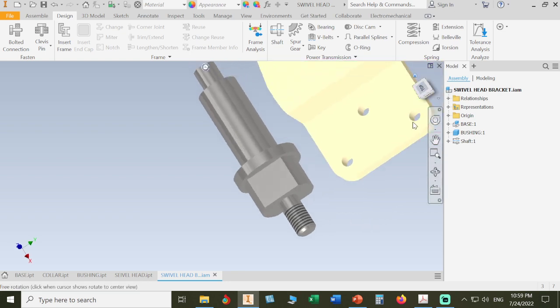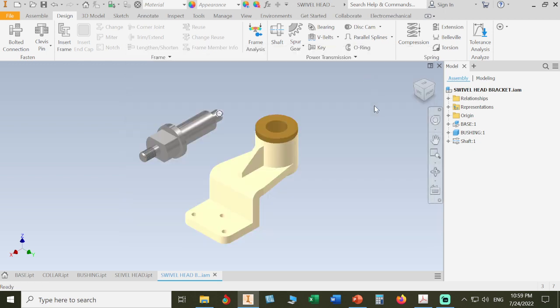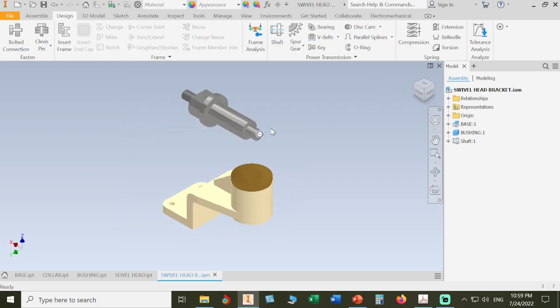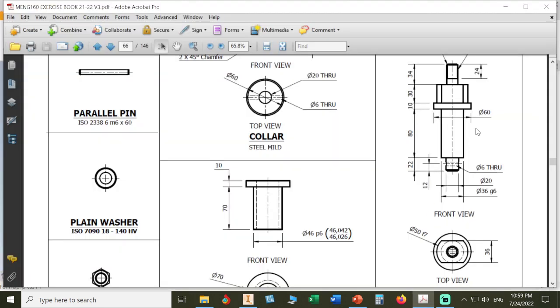Next. Save. Okay. What else can we do with our shaft? Then we have something here. We'll add a chamfer of 2 because it's on both sides, and we have a hole by 6 here in order to put my pin. Then the center of the hole is 12 down, okay, and 6, but we have to put a chamfer.